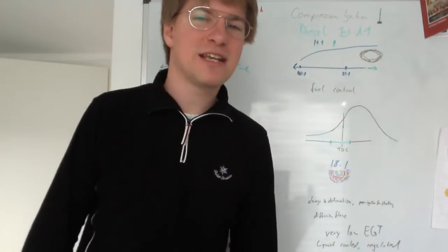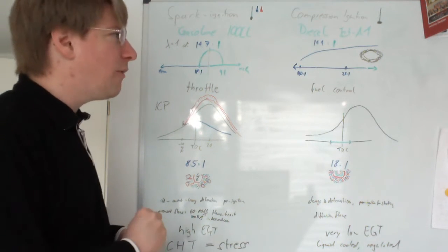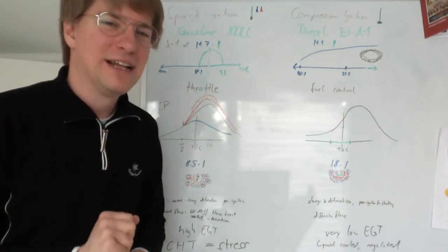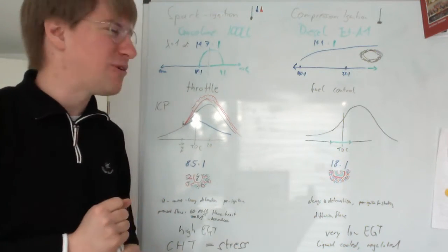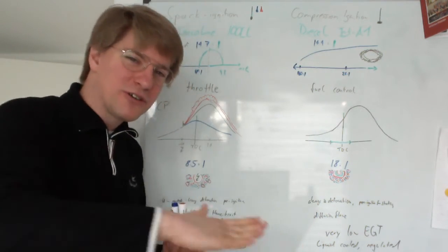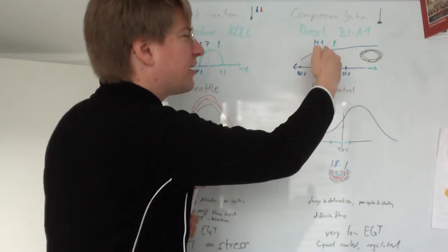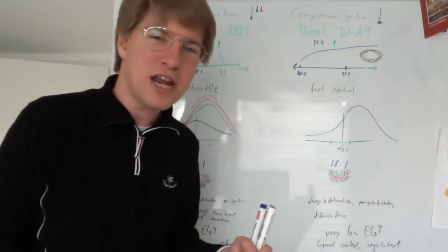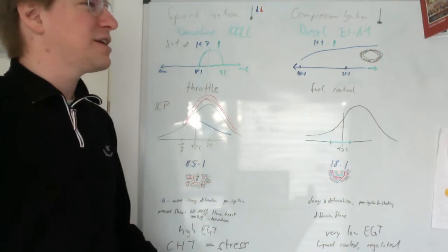So a little bit about this exhaust plume here. If you have a diesel engine that has no electronic control, if you just push down on the accelerator pedal in a very old, like the Mercedes 190D, which is the best car, the baby Benz 190D, best car ever made by Mercedes, but that's a different story. So if you push the fuel control all the way in and you are injecting all that fuel into the cylinder and you move beyond this about 25 to 1 ratio, closer to the 14 to 1 ratio, you are going to make a lot of smoke. There's a lot of smoke coming out your exhaust pipe.